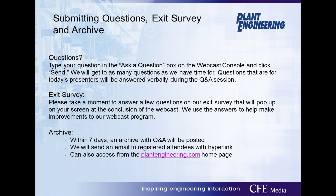That's a good question. In the Compressed Air Challenge, we're recommending 5 to 10 gallons per CFM. And that's with load/unload compressors, to make sure that they have enough time. The receivers originally for the old recips were sized at about 1 gallon per CFM. So we see a lot of undersized storage. And then it got up to like 3 gallons per CFM. But ideally, you want to be in that 5 to 10.